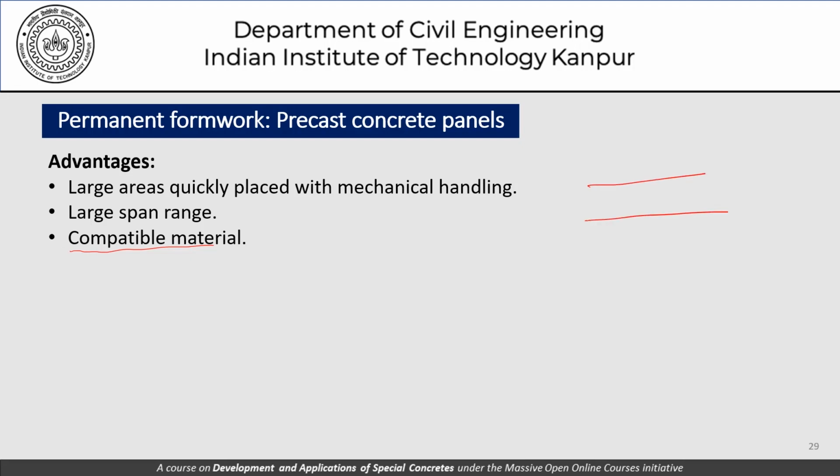Also, we can surely control the permeability of my permanent formwork by using special concretes in these formworks, because we are dealing with a small volume and not necessarily a very large volume, and we could reinforce it with special materials which will add to the impermeable nature or make this concrete more and more impervious, which could be such an advantage when we are really talking about the cover thickness here, because the reinforcement is going to be somewhere here, and this very impervious kind of permanent formwork is equivalent to several times the same cover thickness which is provided for normal concrete.